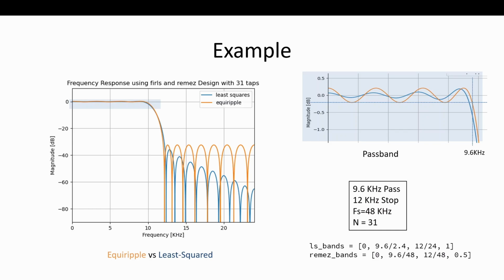That can be your lowest low pass filter, right? 1 over n, it's the reciprocal of the length and time. And that comes up everywhere. Your frequency accuracy is the reciprocal of your length and time, your observation and time, your ability to resolve frequencies, right? So that affects the number of taps. It's how tight it can be.